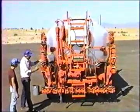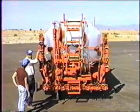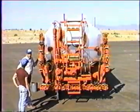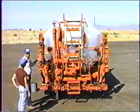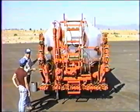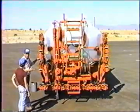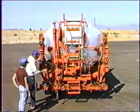Okay, what has happened, the spray bar is opened, the relief valve is closed, the asphalt is always going to take the path of least resistance. It's going to find the easiest place to go. Well, these valves and nozzles have all opened up, so that's the easiest place for it to go. Material is going out of the spray bar.